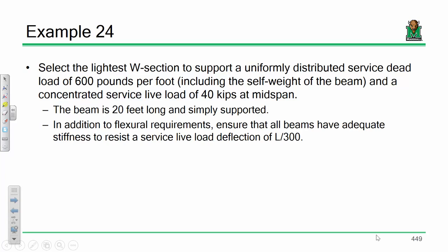Now, we have 3 different requirements that we're going to have to meet regardless of which beam we're designing. We're doing 4 different beam designs, but they all have to essentially meet the same limits. There are 3 that we have to consider: moment, shear, and deflection.